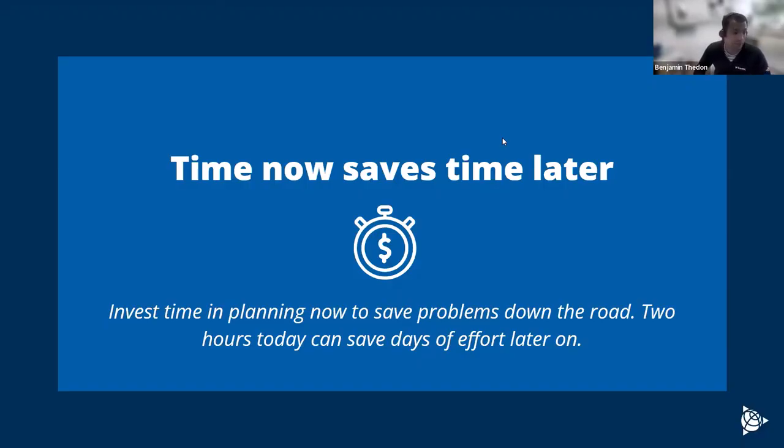It's very important to identify where each sensor is going to be installed and identify on your gateway by name properly your sensor, so you know sensor one goes at this location. Because after, when you have 100 sensors installed on site, you don't know where each one is installed.